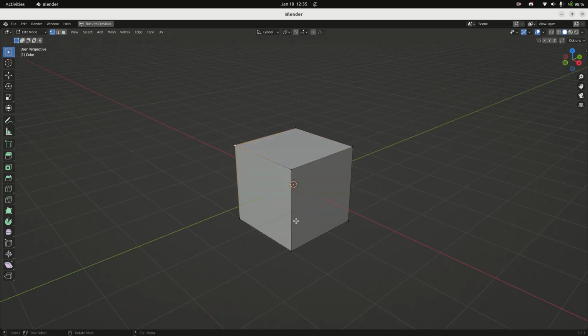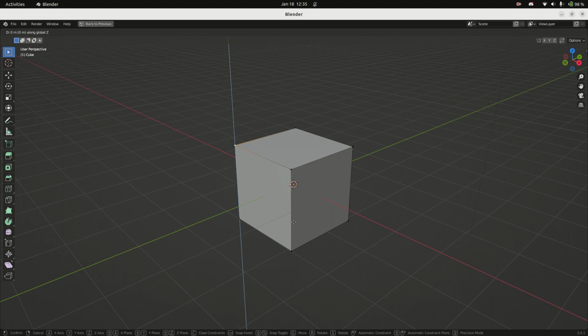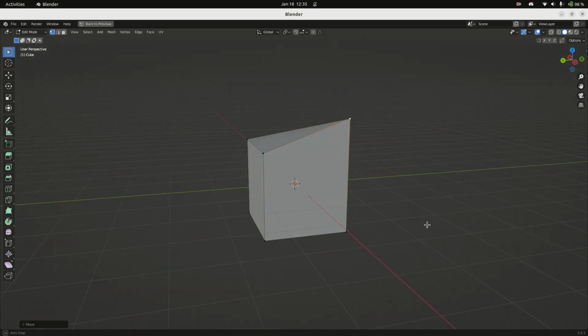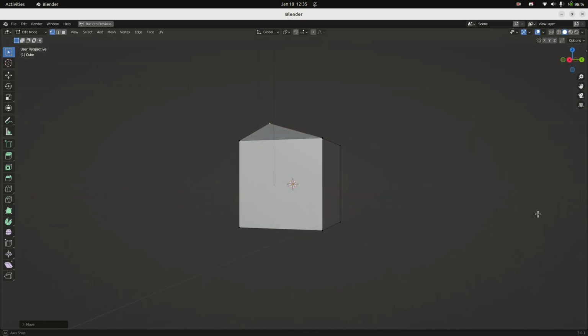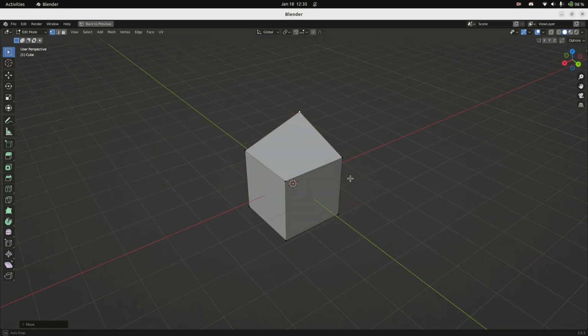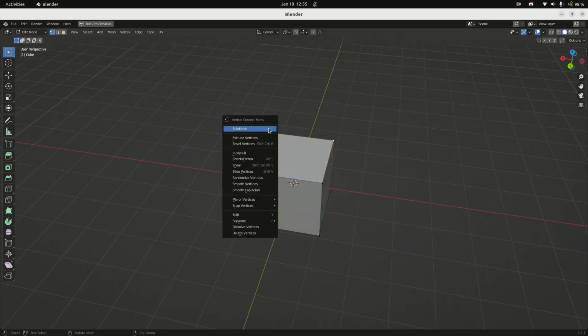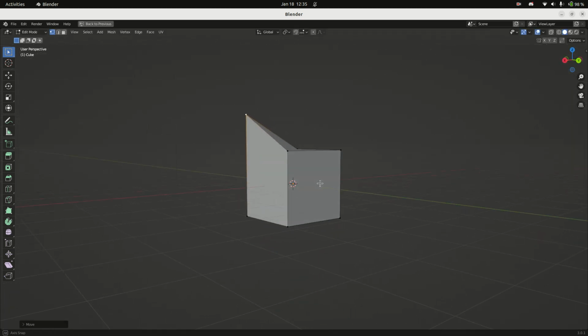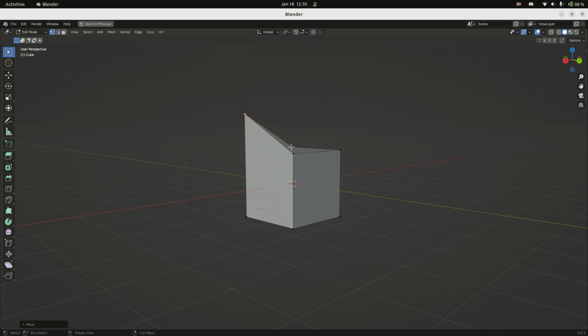If I just select this one vertex and I hit grab and Z and I lift this up, how should it draw this now oblique cube? Does it make this an axis or does it make that an axis? Blender has chosen that's my axis. But if I select that vertex, and I lift it up and I look at it, Blender has chosen this is the axis that is the real edge, and this one is not. Sometimes that can make things look a little weird.